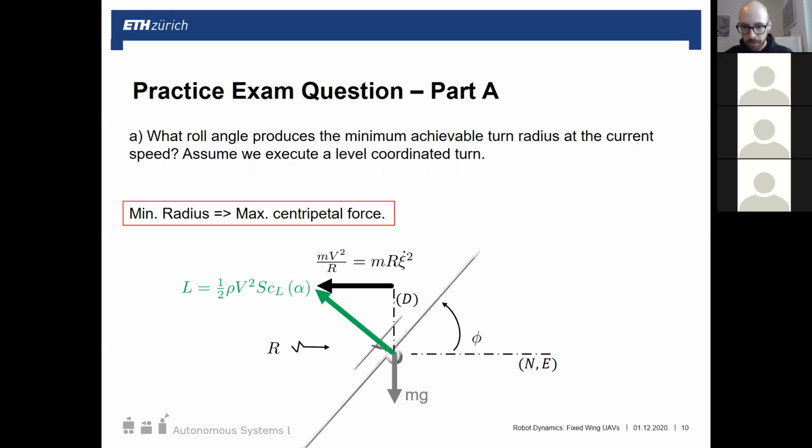How do we define angle of attack, between chord and airflow, or between something else? Another good question. This was answered in more detail on Piazza, but I'll quickly answer again. I think the confusion comes from the first video segment, where 2D airfoil analysis was shown, looking only at the cross section and the airfoil itself. In 2D airfoil analysis, the angle of attack is between the flow and the chord line.